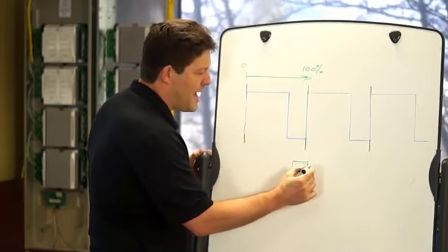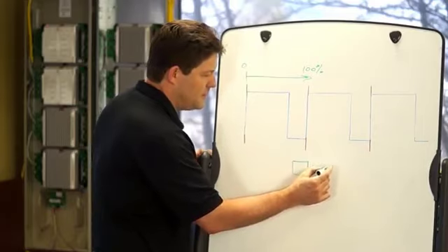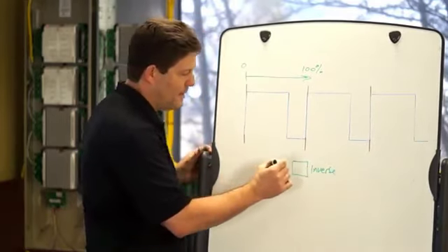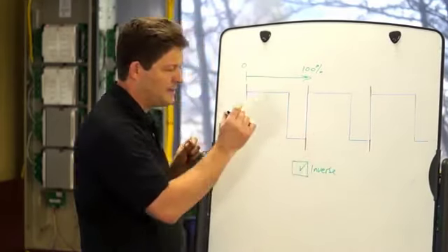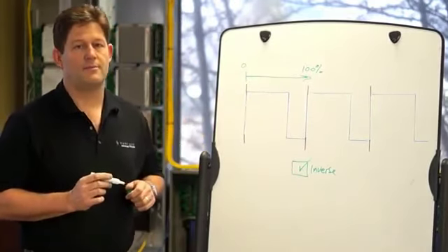Now, this non-compliant light source, if you're going to control that from within Vantage Design Center, there's a box that says inverse that applies to this light load. And you are going to select that, meaning that it is non-standard.